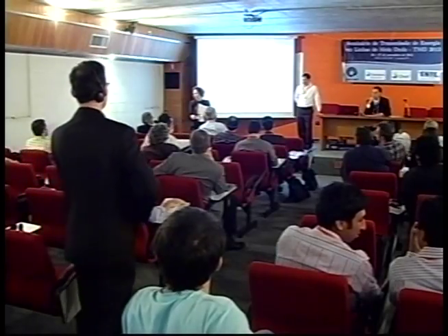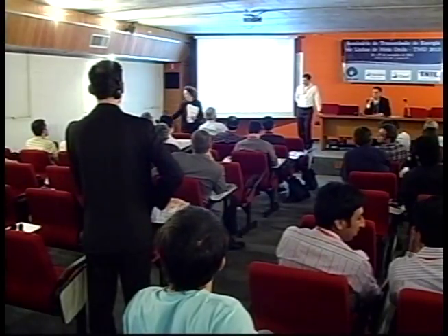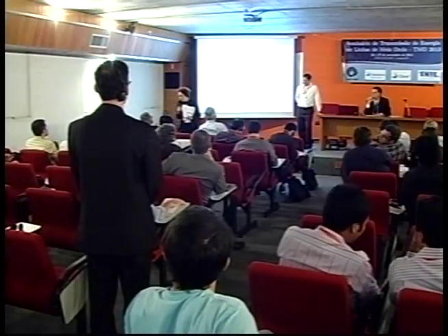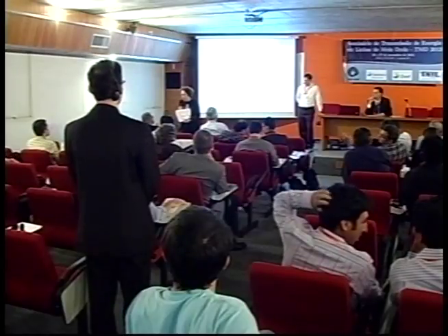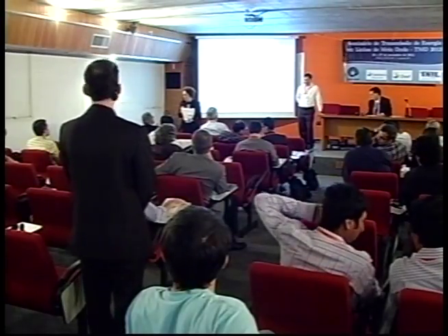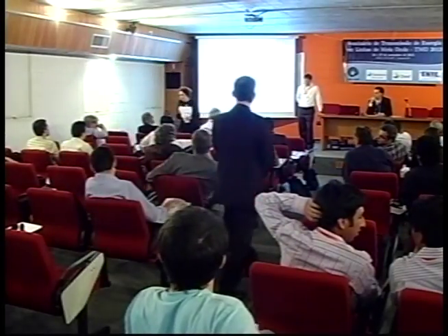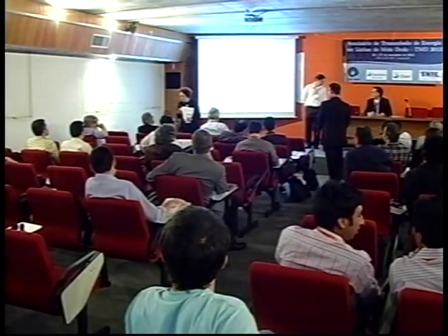If you did the Marti in the ATP, would it become closer to the PSCAD value? The Marti model can be unstable, so we cannot use it. We do not trust the results. It can be closer, but there can also be some differences in the results, although we are working with an ideally transposed line.